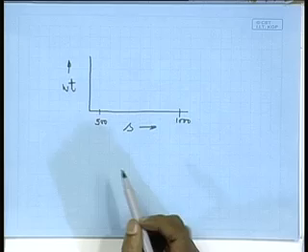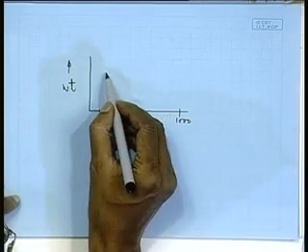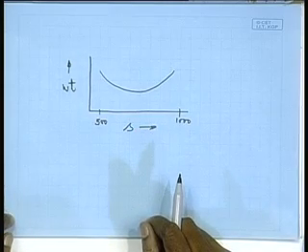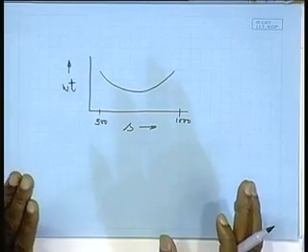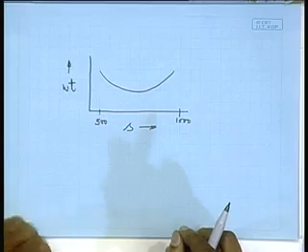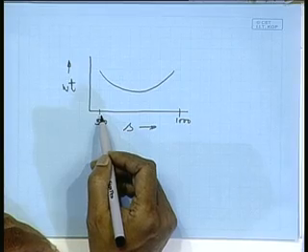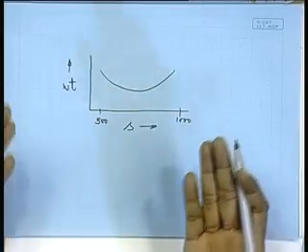So, how would the curve be expected to look? Well, possibly something like this. I do not know, I have not done this exercise, but what I have drawn shows that, for a given case, it is not a universal truth, for a given loading condition and a given plate material, providing a frame spacing as low as 500 and as high as 1000 both give a higher weight of the structure.